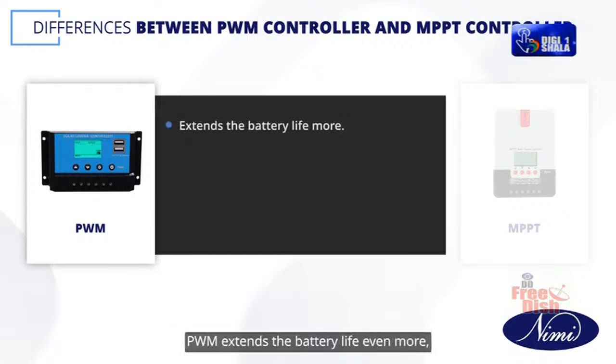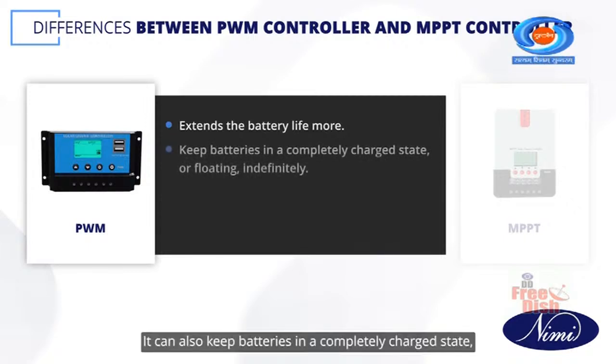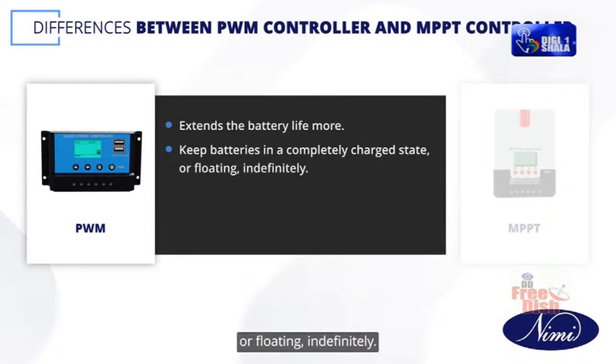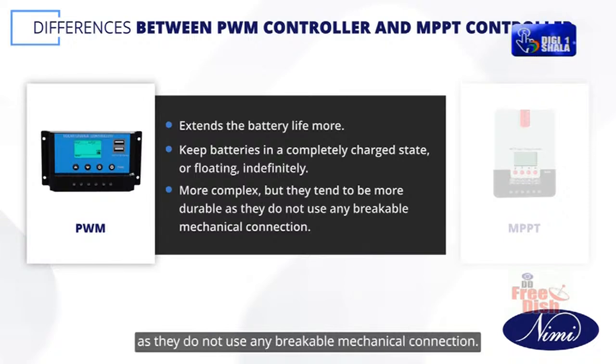PWM extends the battery life even more as it decreases stress on battery. It can also keep batteries in a completely charged state or floating indefinitely. PWM chargers are more complex, but they tend to be more durable as they do not use any breakable mechanical connection.